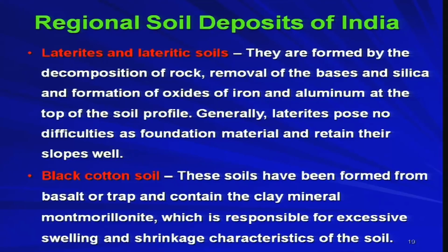It contains the clay mineral montmorillonite, which is responsible for excessive swelling. If you add water, it will swell excessively, and if you take out water, it will shrink excessively. That means swelling and shrinkage, both are excessive in this kind of soil. That is why it is a very problematic soil.